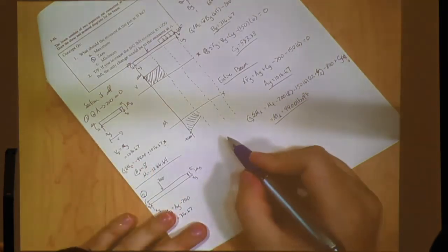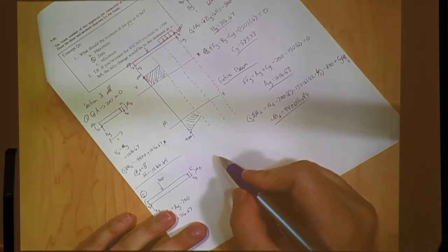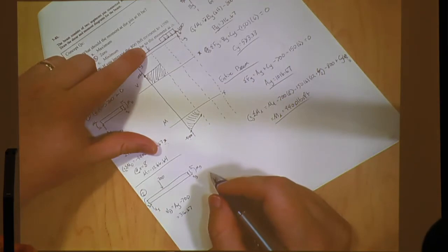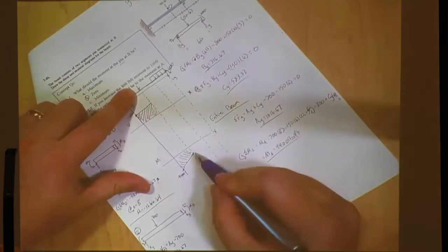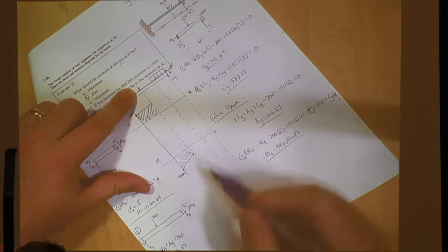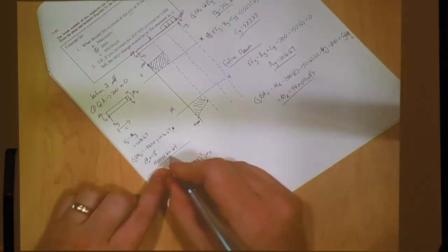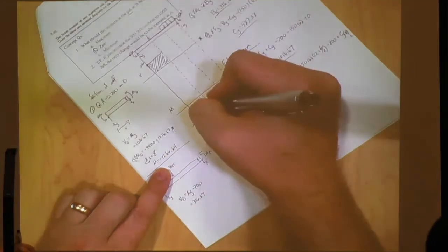Each section of the beam where external forces change or you have a reaction force, you're going to have a different equation for the line. It stops right here at this section because now we're taking into account the external load of 700. And it's going to change this. We stopped at negative 1266.64. Sorry, I should have labeled it.